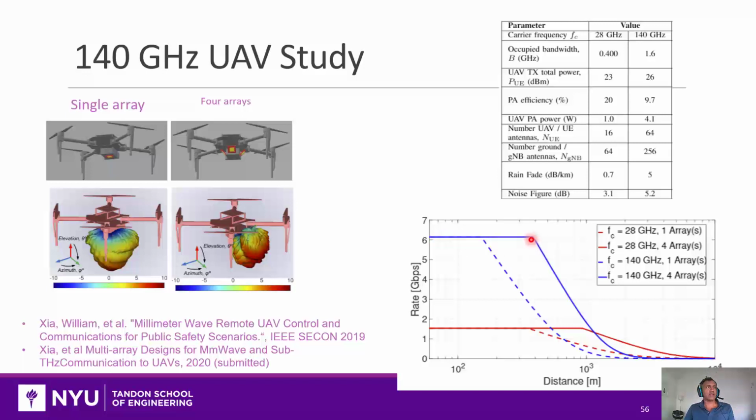You can get over 6 gigabits per second, and you can get over a gigabit per second well out into 100 kilometers, and that could do significantly better than a system at 28. So if you need these very nosebleed data rates, this might be an attractive way. If we add line of sight MIMO on top of this, which I did not show, these will go up even quite significantly, because as we saw before, when you're in that few hundreds of meters of range, you're easily in that Rayleigh distance.